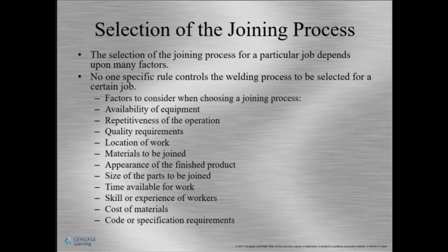How much time do I have to complete the welds? Is it a day, a week, a month? How many do I have, so I know exactly how big this project is? What is the skill level of the welder? Can the welder do this? What is the cost of the particular materials? And are there specific codes or standards that must be taken into consideration? Under those codes, you may need to be certified to the particular code in order to perform the work.